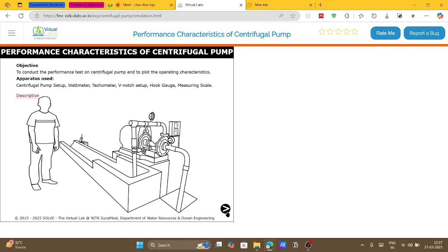So basically here I am not focusing on this part much, because the overall idea is for you to understand how this experiment is being performed, and to gain the understanding of the experiment and what we are learning here, right? So this is the diagram for our experimental setup. Water is drawn from this well. It is going into our centrifugal pump. So there is this pressure gauge at the suction, and a pressure gauge provided at the outlet, the discharge, right? There is this valve which is connected to discharge.